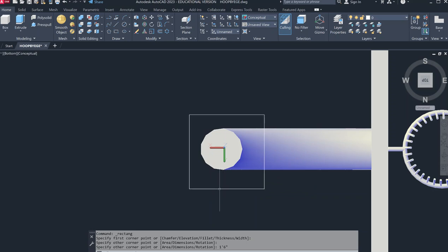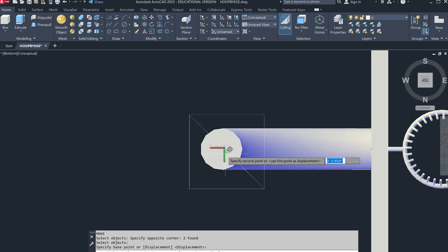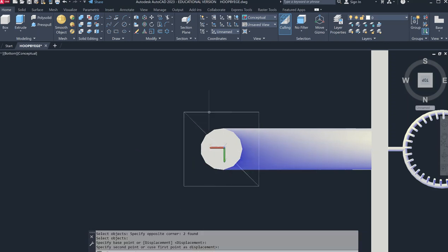And again, centering is the problem. So draw a line from one corner. The computer knows where the center of the line is, so I don't need to draw two of them. I'm going to move this object from where it is. So I need to pick the center point. It shows me the center point with a triangle. Now I'm going to use the center point of the circle. Click. Perfect. I'm going to erase this line. I don't need it anymore.